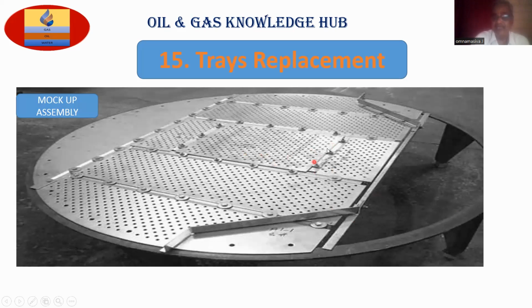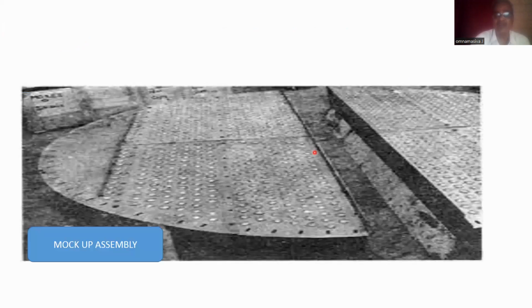Once you open this, from the bottom side you come out to the upper side, then close the manway and put the ladder. Scaffolding, because you cannot go down again, and you should not leave anything below this tray. Next, stage by stage, one tray, the lower tray first, then the second one, from the bottom, you have to install.